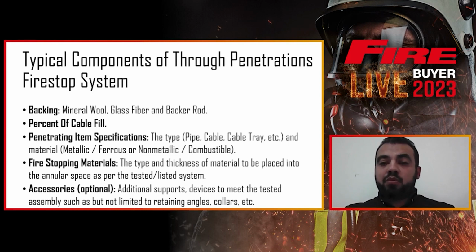Plastic pipes will melt and will not stay for a long time, so you need to use a sealant material that will expand and close the hole. Metallic pipes normally will stay in place, but may have minor deflection on the surroundings that will need a sealant to stay in place, with no need for expandable material like for plastic pipes or cables.